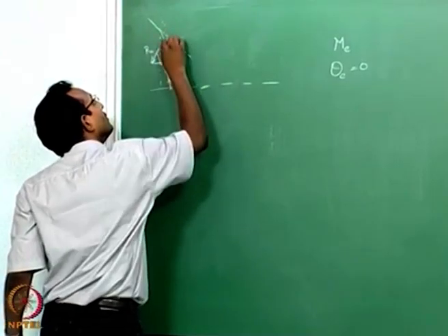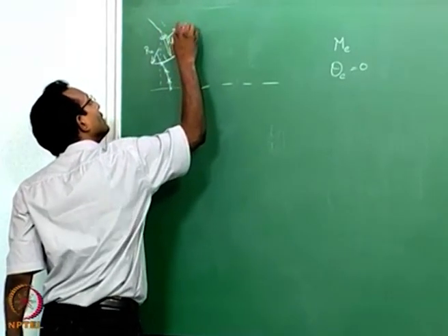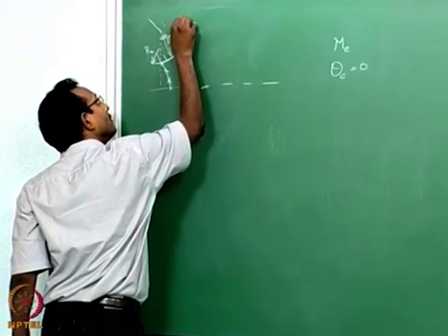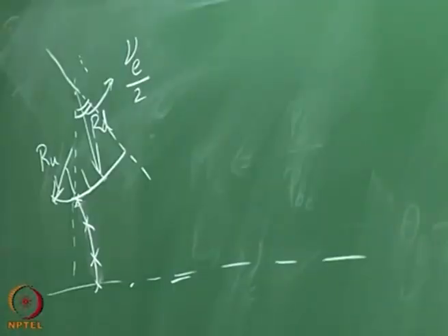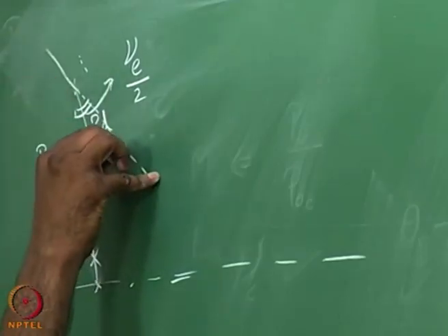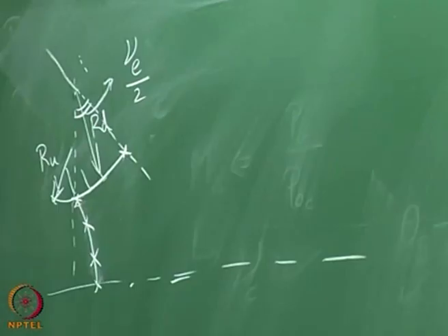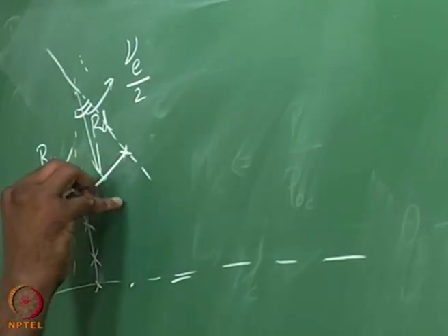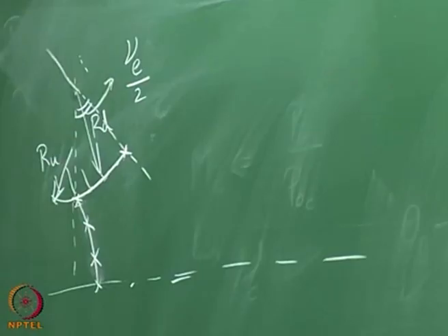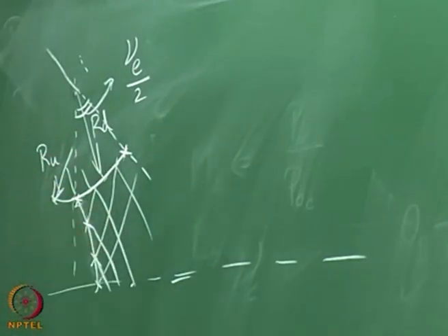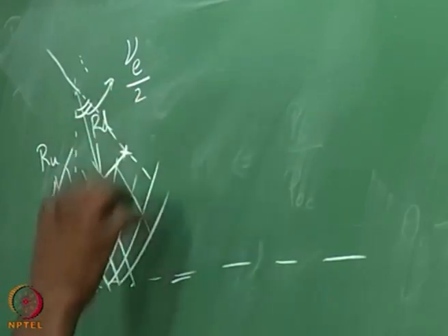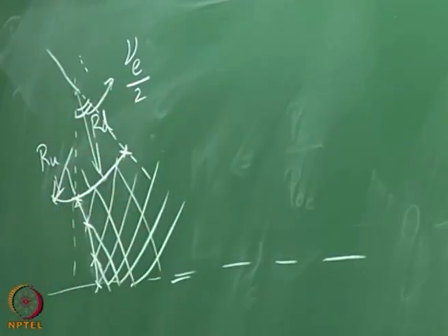this angle comes out to be nu exit by 2. Why? We will see it in a minute. Okay. Say if that is nu exit by 2, that is my last point on my wall. Okay. I have created a wall along this where I have so many points on this wall. Now, of course, I can start calculating characteristics from here and go back and everything. That whole set of things can be done from here.